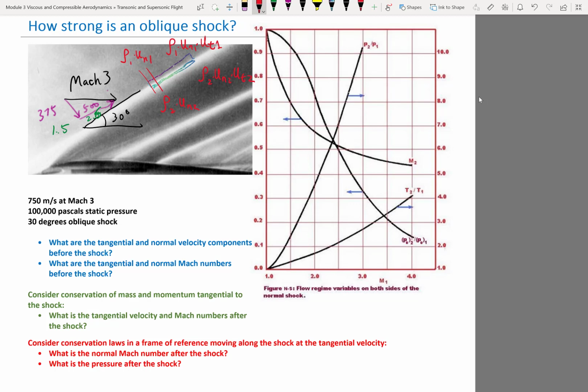Well, in this flow, this control volume doesn't touch any solid bodies, right? So there are only forces within the flow. There is viscous force and pressure force. First of all, viscous force is non-negligible within the shock. But here I have carefully drawn the control volume so that both sides are actually outside of the shock, right? So there are actually no viscous forces except for maybe just at this point, right? But this point is going to be so small that it probably doesn't matter. I've drawn this to be very thin.